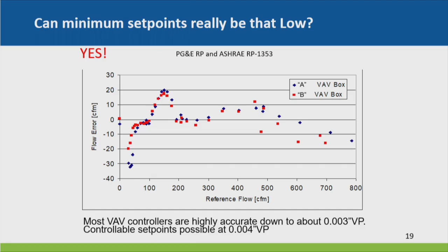And so we do research, and we find out that that is wrong. We also found that VAV box controllable minimums are much higher than most people think. The research project showed that we could get down, this is for an 8-inch box, to 50, 40 CFM before it starts dying in terms of accuracy. So we tested every single manufacturer's VAV box controller there is. Some were better than others, for sure, but most of them were pretty good.